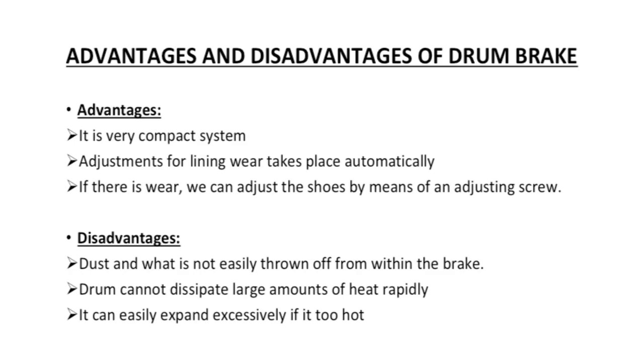Disadvantages: dust and water are not easily thrown off from within the brakes. The drum cannot dissipate a large amount of heat rapidly, and it can expand excessively if it becomes too hot. So those are the disadvantages of the drum brake.